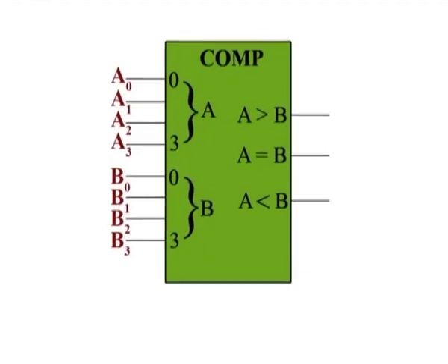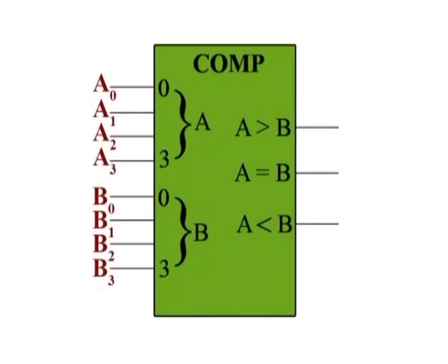These three operations are valid for each bit position in the numbers. The general procedure used in a comparator is to check for an inequality in a bit position, starting with the highest order bits. When such an inequality is found, the relationship of the two numbers is established, and any other inequalities in lower order bit positions must be ignored because it is possible for an opposite indication to occur. The highest order indication must take precedence.